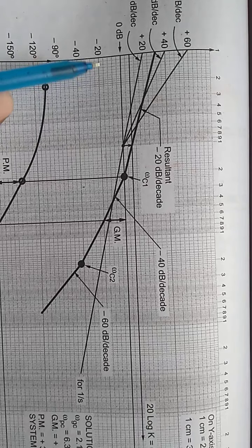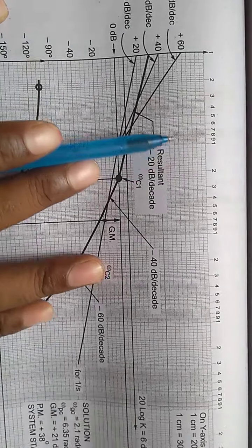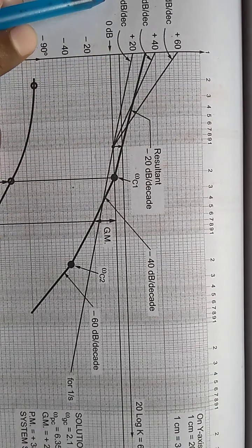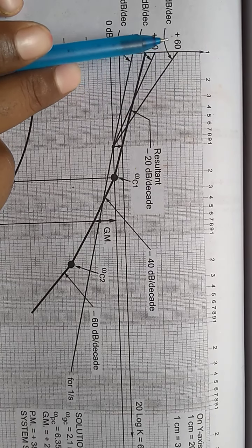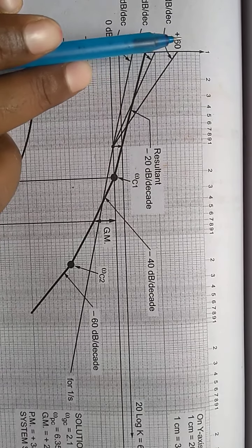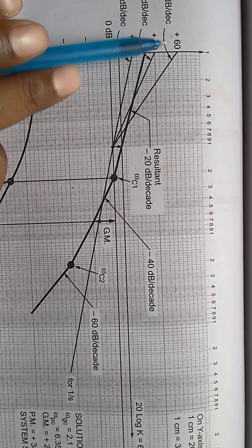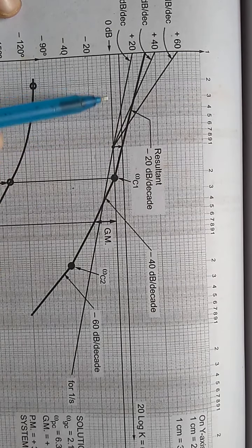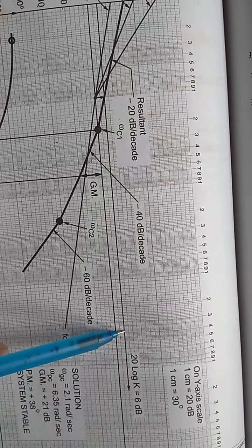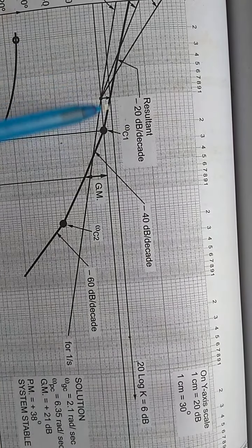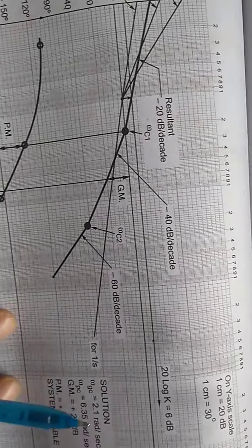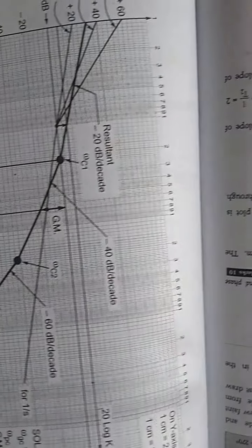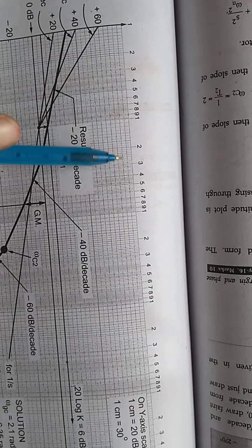So look at here. That is the 0 dB. As I told you, with a similar procedure, here we have drawn the graph. This is 0 dB. Mark the points minus 20 dB, minus 40, minus 60. But as usual we have values in the upper quadrant, which are positive. But actually as per the procedure, this slope line will be different. And here minus 20, minus 40, minus 60, and so on. Then you have to draw the 20 log k slope line. Have you observed this 20 log k? So that will be drawn. Then here you can mark the phase angle plot, the 180 degree line. And the frequencies in the top corner, we are observing, these are all the frequencies.